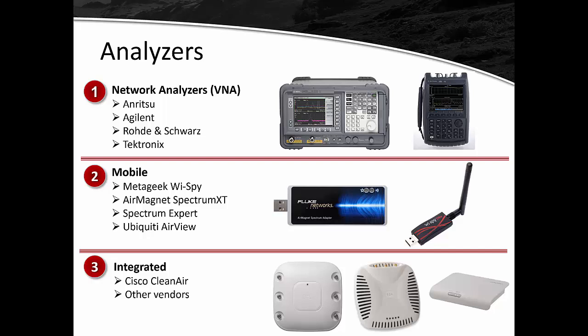Now, it is important to know that the spectrum analyzer may do integrated protocol capture or protocol analysis. If that's the case and you want to use those integrated features, then yes, you may actually need to update the software, but your adapter should still work because the adapter just looks at the RF energy. And whether that RF energy is being generated as a single stream, 2 streams, 3 streams, 4 streams, it really doesn't matter. It's just RF energy. It may look a little bit different, but it's just RF energy. And so the answer to the question, do I need to update every time I move to a new version of 802.11, of course, is no.